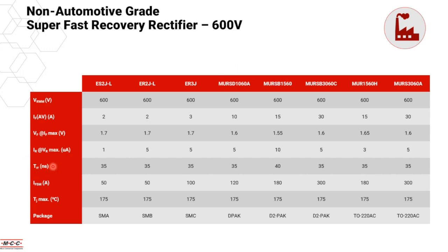So this is the TRR that we mentioned just now. This is the reverse recovery time. You can see this is super fast, which we target at less than 150 nanoseconds. The TRR mentioned over here is about 35 nanoseconds.